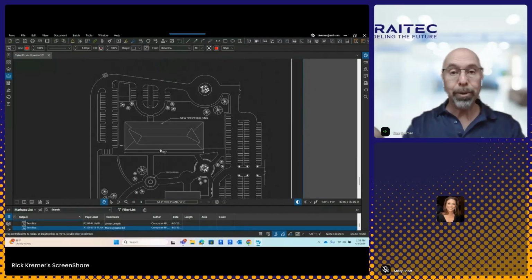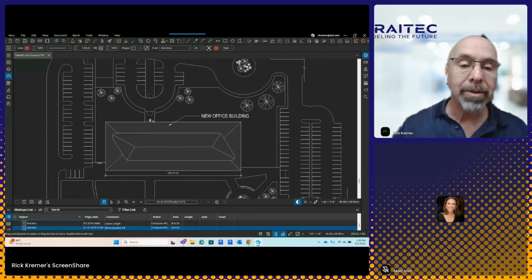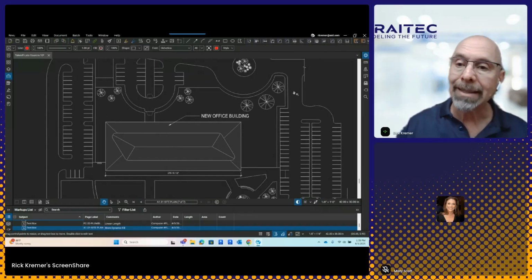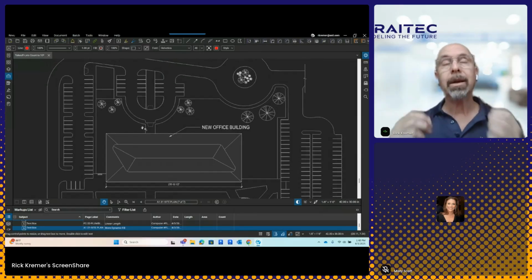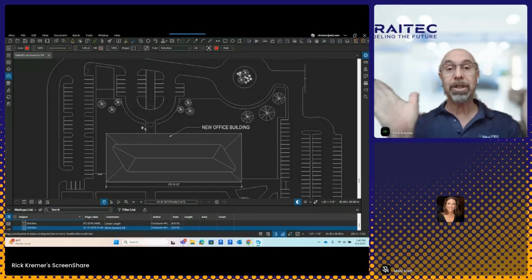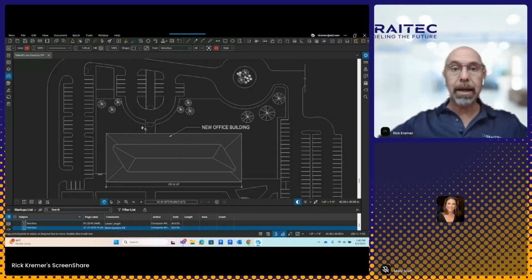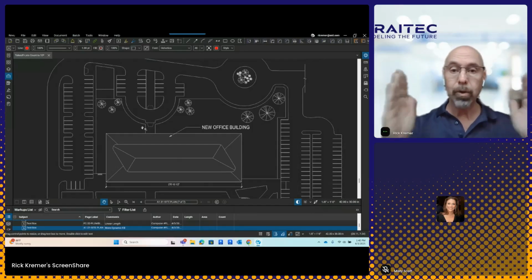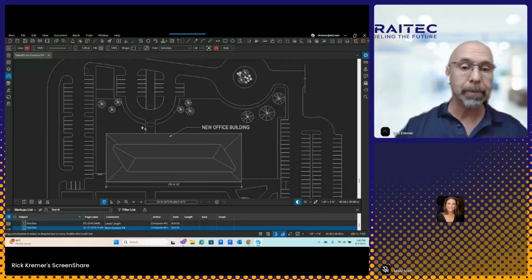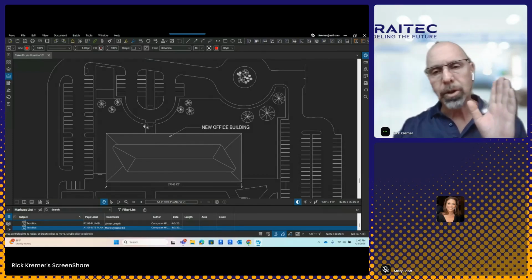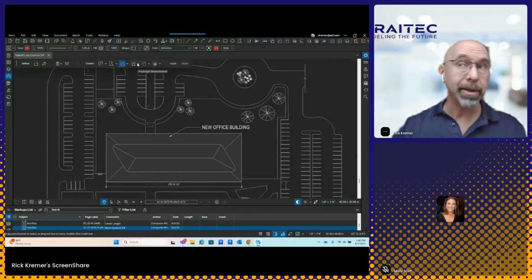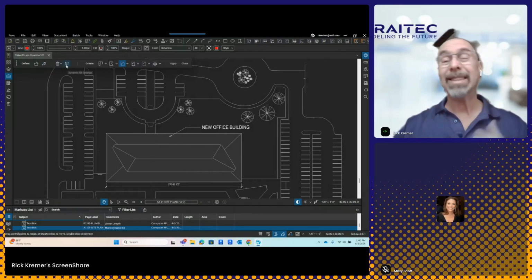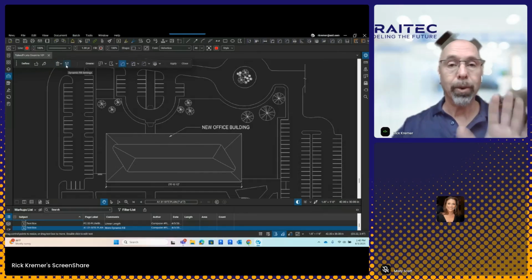All right, back to the asphalt. Over here, I have sidewalk that is as curvy as it gets, and I need to go through and calculate how much it is. Here's the caveat. When doing this, think of the concrete pour as having to have solid sides so it doesn't spill out. Just like you would do a regular concrete pour, you need some type of wood blocking, right? So we're going to do the same thing here. If you don't, there's solutions and workflows around that. But I'm going to type in J, which is the shortcut for dynamic fill. And over here, I'm going to do dynamic fill. One of the things I like to do, which I recommend, is slow it down.